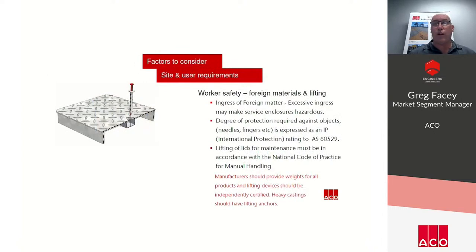We also need to consider the worker safety of foreign materials and lifting, so the ingress of foreign matter. So excessive ingress may make the service enclosure hazardous. A degree of protection is required against objects, so needles and fingers, for example, and that's expressed as an IP rating to AS 60529. Lifting of lids for maintenance must be in accordance with the National Code of Practice for manual handling, and manufacturers should provide for all products, and lifting devices should be independently certified, and heavy castings should also have lifting anchors.